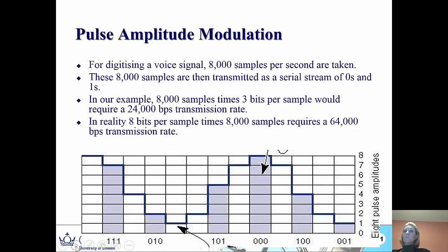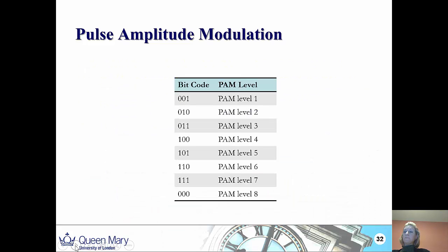Okay, so these are baseband signals. A baseband signal is typically a signal which has a very narrow frequency range, and they can be transmitted without any modulation, without any shift in the range of frequencies of the signal. They are of low frequency, so they're contained within the band of frequencies from close to 0 Hz up to a higher cutoff frequency or maximum bandwidth. Okay, so this is how we think about converting this signal into a digital signal for communication. So we've got a series of levels, and with each level we have a certain bit code which represents the value at each level.